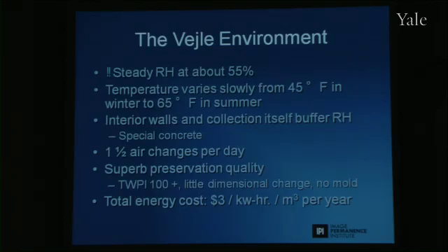Here are some of the secrets to making this building do its magic. It has no outside air. There's no intentionally introduced outside air. From leakage, the doors opening, and so on, they have measured it to be about 1.5 air changes per day. So the inside air is replaced by outside air only 1.5 times a day. Does that sound like a lot to you? A building like this probably undergoes 17 to 20 air changes per day. The room we're in, so that's very low.